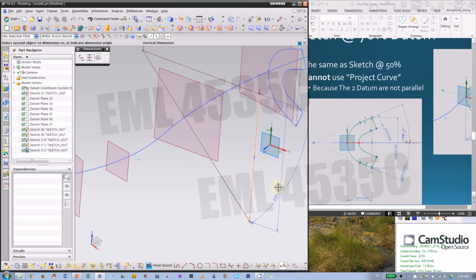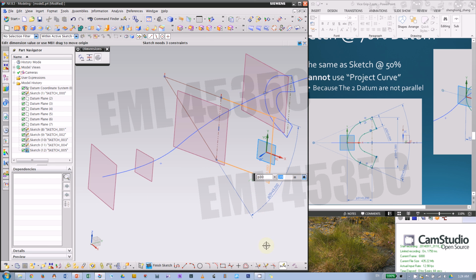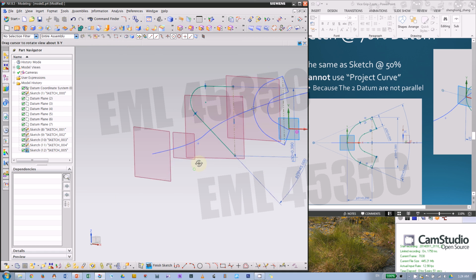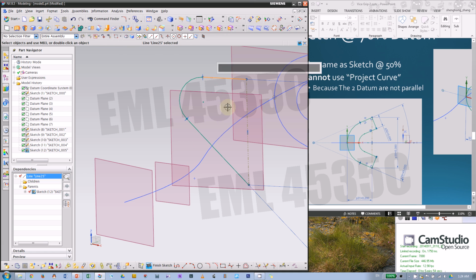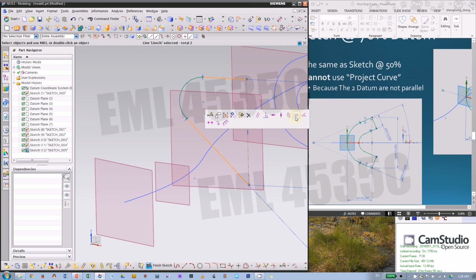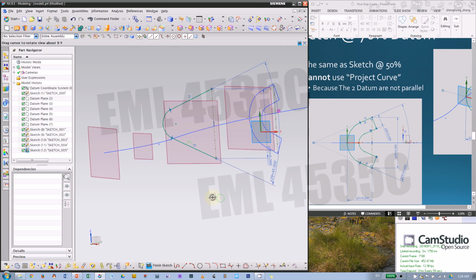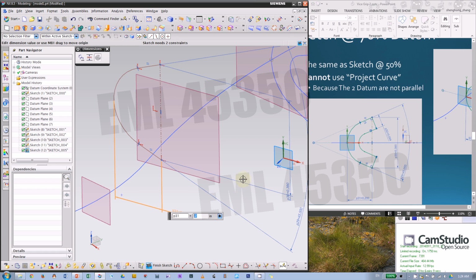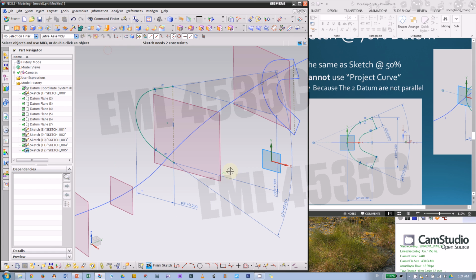And opening width of this C is 0.39. And let's make a fillet here. Okay, so it's not equal at the top and the bottom. And pick them up in this quick menu, make them equal. And now we can give a dimension between this to the arc, which is 0.2 inch. That'll be enough.